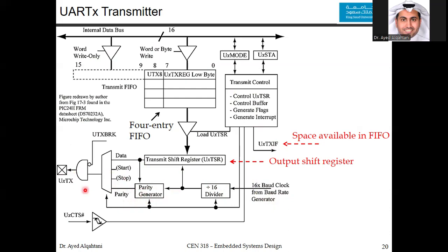If you use flow control, the transmitter should expect clear to send from the receiver. Anything that comes as an input should be first accepted by a Schmitt buffer, so you make sure the edges are sharp because maybe you will have noise or something like that. This is the way of the transmission.